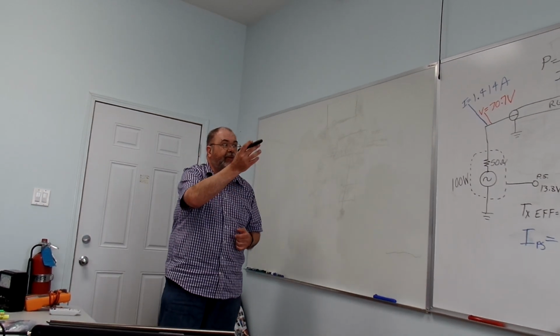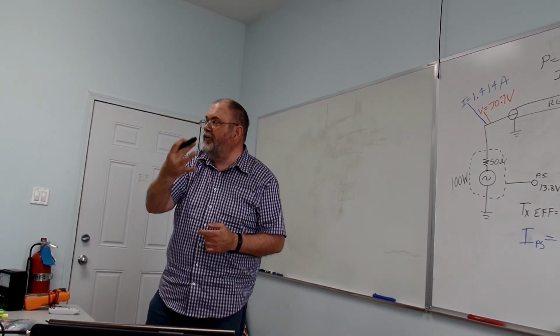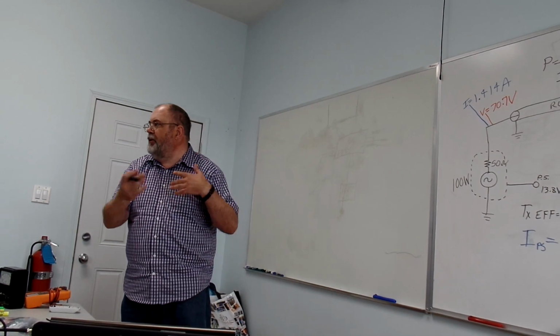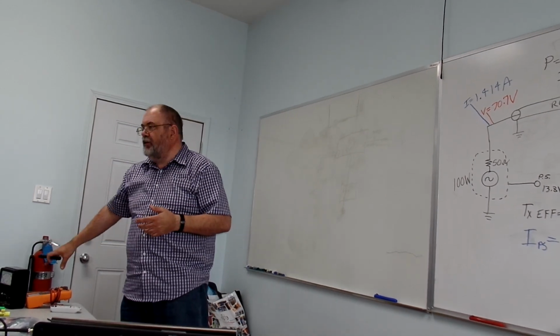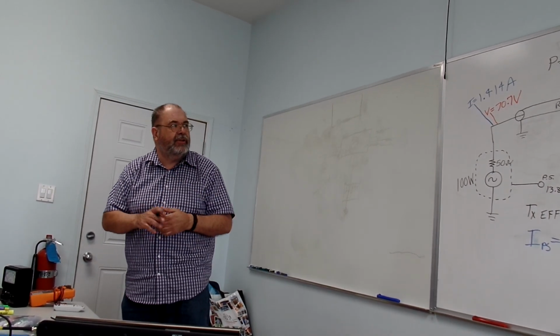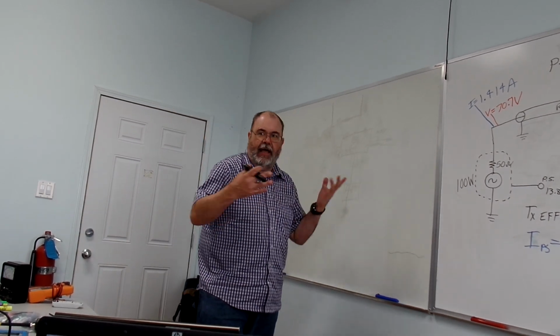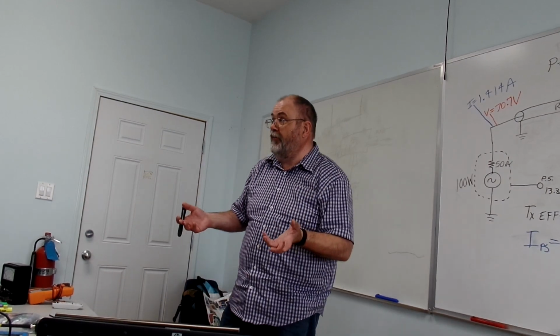So the antenna impedance can go above or below 50 ohms and give you reflected things. And there is a way mathematically to tell which way it's going. Little antenna analyzers can do that internally. They can say it's higher or lower impedance and stuff. But that's what happens. And how fast does this happen? Well, it happens bloody fast.